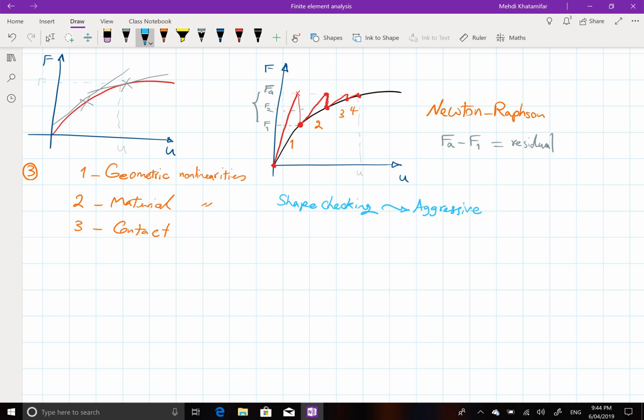So by changing this option to aggressive, ANSYS is going to make sure the quality of the mesh is much better, and it is going to anticipate the distortion of the elements we have, because we are supposed to have a large deflection, and when we have large deflection, those meshes are going to stretch and create a lot of trouble and failure. So ANSYS is going to make sure we have better quality mesh, and sometimes it is going to work just with changing this.